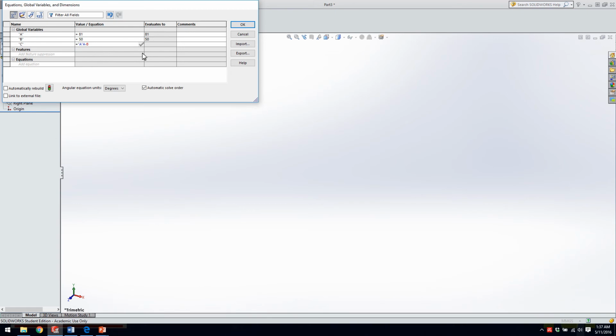What you'll notice is that when you type variables into these equations, they need to be surrounded by double quotation marks. And the variables will be slightly blue. That's how you know they're going to work, and this checkbox will be green. So you can make variables that are functions of other variables or numbers. You can add 10 or whatever you like.